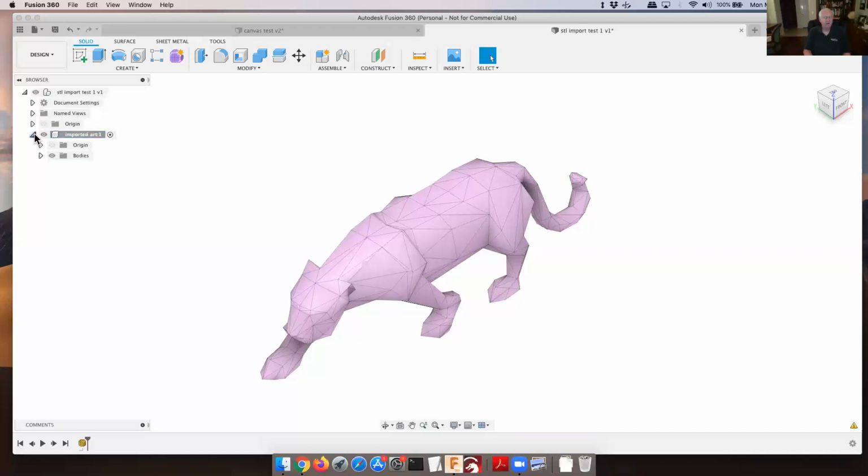You have your timeline going. Oh, right, that's why, because we have to get rid of the, thank you. That was the other nuance. The other nuance is the modifications that we're doing to meshes, we can't keep the history. It's what's called DM, or direct modeling, in Fusion 360. And it's more like probably SketchUp is, where you do things, you don't go back into your timeline and make changes. So in fact, Tim, working with meshes, you can't even use the timeline.